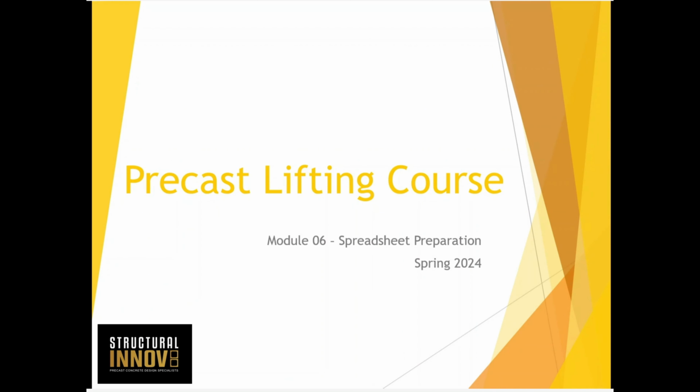Okay. So we've covered quite a bit up to now. Lifting, how to calculate the lifting demands, the lifting capacities, tension capacity, shear capacities, the different types of lifters. Some worked examples, lifting with rebar and strand. And now, in order to be able to use this kind of information going forward, the best thing to do is to develop a spreadsheet that will take various inputs and geometry, etc., and give you a design.